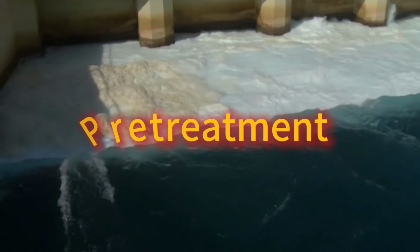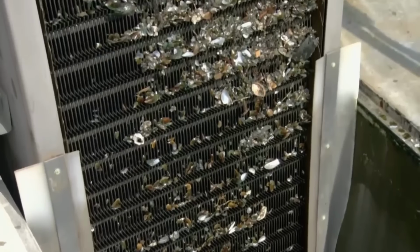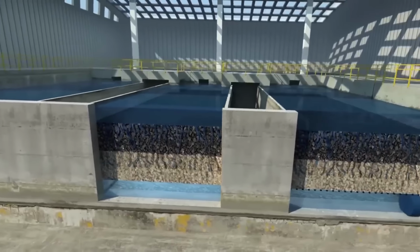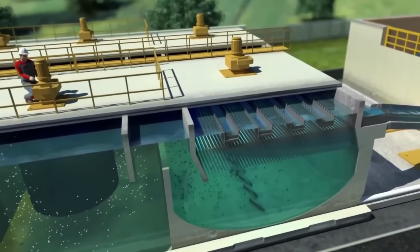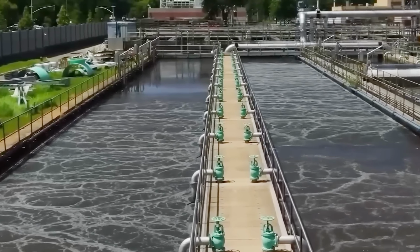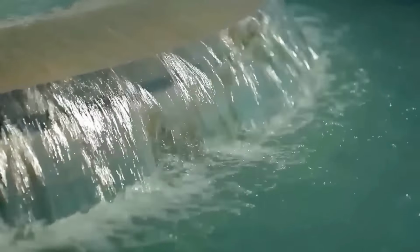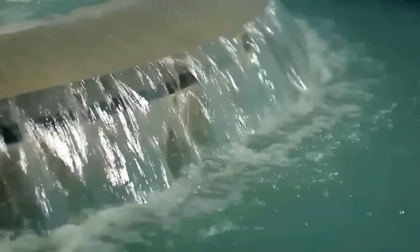The exact process varies with local seawater conditions. Larger particles can be removed by conventional media filters, while some modern plants use microfiltration or ultrafiltration membranes to catch much smaller particles. Chemicals may also be added to help suspended material clump together, control microorganisms, or prevent minerals from forming scale later inside the reverse osmosis system. By the end of pretreatment, the water may look completely clean, but nearly all of the dissolved salt is still there. Removing that salt requires the most important part of the plant.